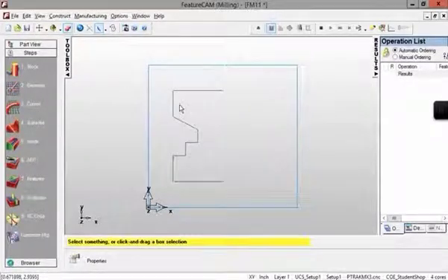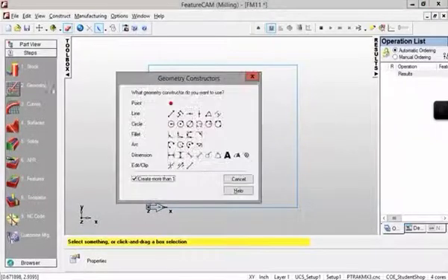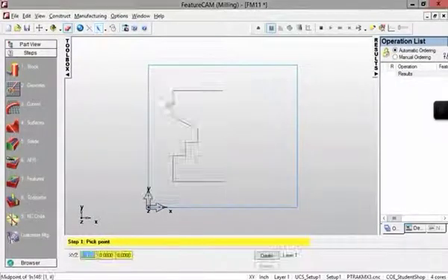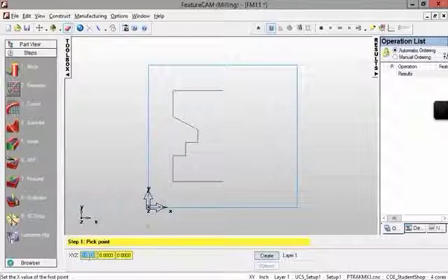Okay, after you finish the line segment drawing, we are going to draw some points for the holes on the corners. You always select the geometry button and then click the point. Okay, and you put in the coordinates of them. The first point is 0.5, 0.5, great. And the second point is 0.55. Great. Okay, so you can see there are two dark dots at the corner part of the material. And with these dots, we can therefore draw circles to represent the holes.